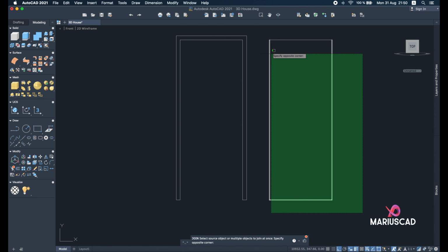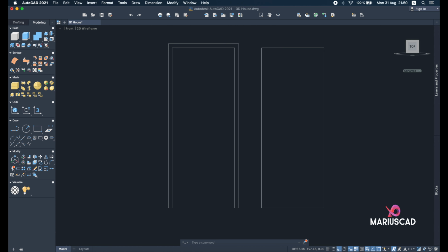Line command, join, and now a part which is very important, draw a line exactly from the middle, because it will help us for our model. And I repeat, it's just a model, a simple one, so don't take it that it is the only model that you can draw. So right now a line with the length of 8.75 units, so centimeter that means. Now rectangle, right now 70 by 110. Place it exactly in the middle.